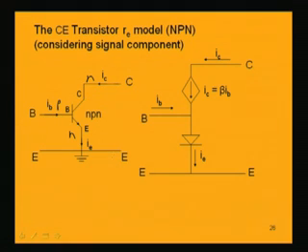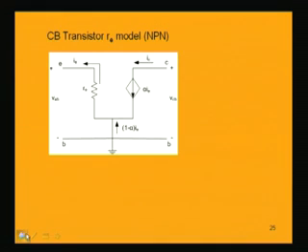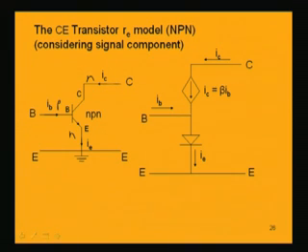But one thing to be noted here is the point of joining between the input and output circuits. In the earlier case, for the common base transistor, this point was grounded, common between input and output, but here this point is connected. The current flowing through this diode is the emitter current IE. This is the input current IB, this is the collector current, and both join at this point. So, the total current, IB plus IC, is the emitter current.